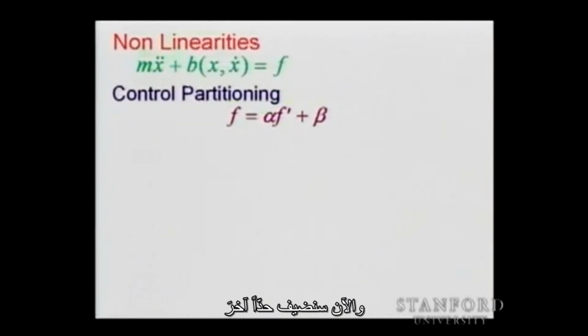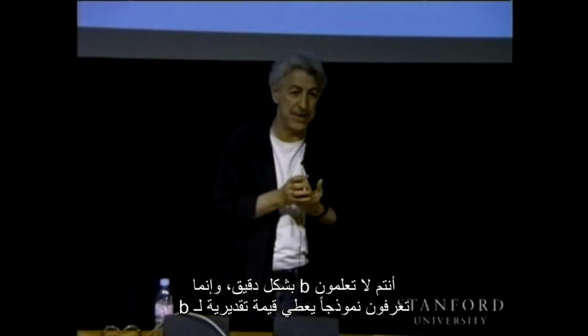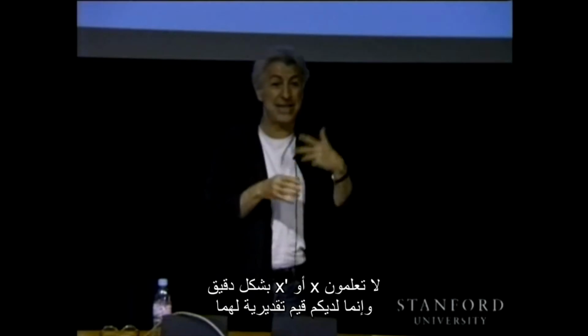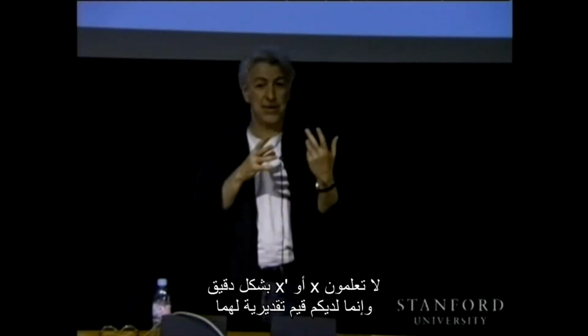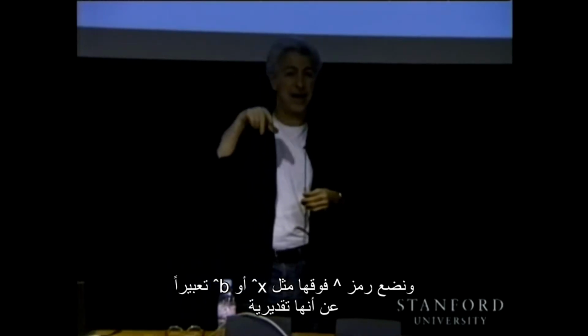And now we are going to add another term, beta, which will attempt to compensate for B. You do not know B exactly. You know sort of a model with some estimate of B. You don't know X exactly, you don't know X dot exactly, you have estimates of these. What we call the X hat, X dot hat, and B hat.